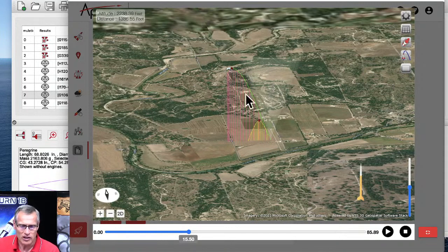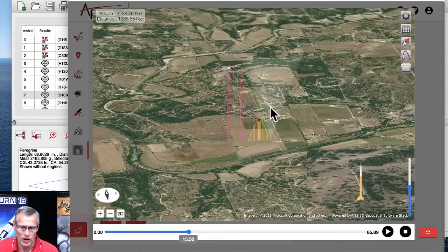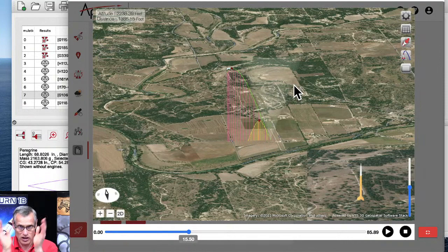That tells us that we're outside the weathercocking cone. You can kind of see this weathercocking cone right here. It's this lighter shaded area. That is a 30-degree cone, and we want the apogee point to stay within that cone, because that means the rocket's going more vertical than sideways, because the safest position is always up. Both the booster stage and the sustainer stage are outside the cone.